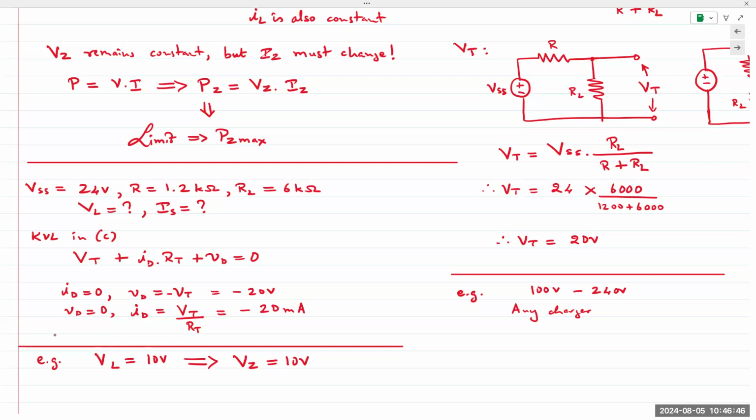Make sense, right? But we have a current limiting resistor in series. So we have to account for the fact that when current flows in the system, that resistor R is going to drop some voltage across it. So we have to add that to the 10 volts, so Vin has to operate at a voltage slightly higher than that. Otherwise, the Zener diode is not going to turn on. If you apply 5 volts, the Zener diode is not turning on, just 5 volts would appear at the output. That's it. Nothing else would happen.